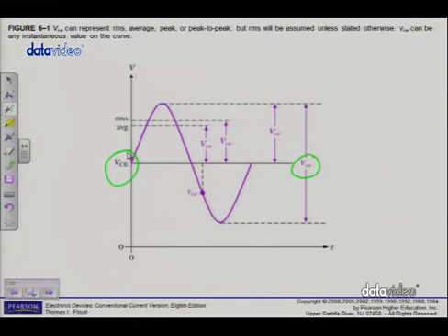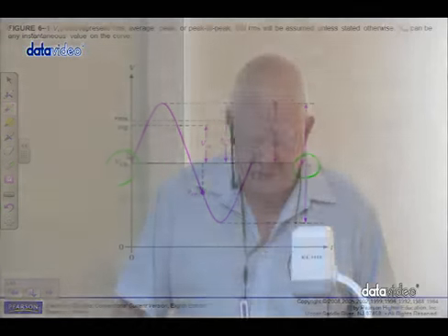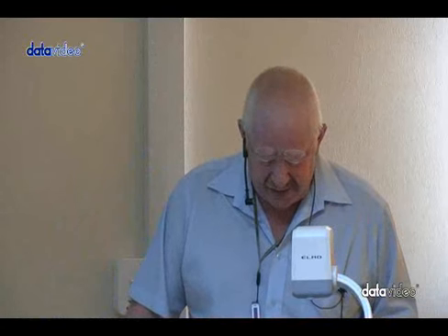Instantaneous quantities are represented by both lowercase letters and subscripts, as you can see there, small i and small c and so forth. Just below the figure, we can also see, for example, rc with a lowercase c is referring to the AC resistance at the collector, and RC with a capital C, of course, refers to the DC quantities.